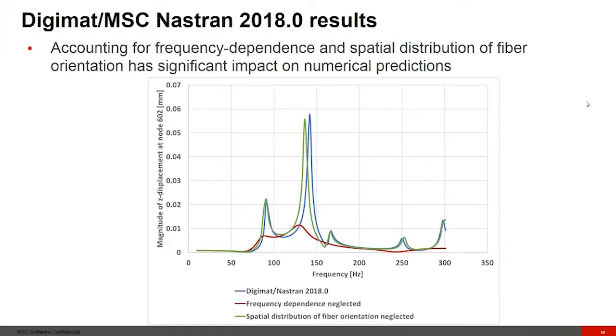We've also improved output for a complex eigenvalue analysis, in which case we correctly identify rotor whirl type for each rotor in the model for both synchronous and asynchronous analysis. We've included cross-coupling terms for an enhanced PBUSH2D entry, which can be used for bearing analysis and such. We've also added SEDAMP handling for correct modal damping in super elements. And finally, in this version of MSC Nastran, we support rotors in part super elements. We'll talk about that a little bit more.